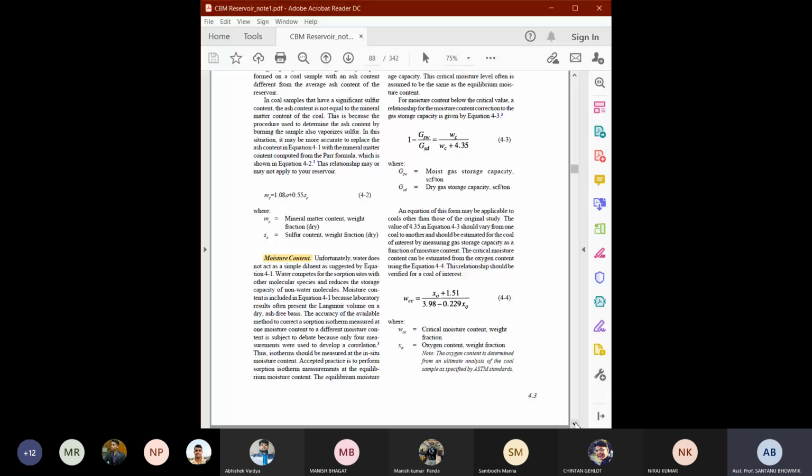When you estimate the moisture content of the sample, you will see that the 10% moisture is remaining there, okay. But when you prepare the dry sample, following the standard test procedure, you will find that you will not be able to reach 0% moisture, okay, because there is some connate water, some inherent moisture, already there.